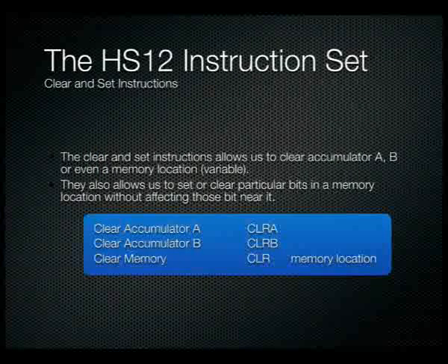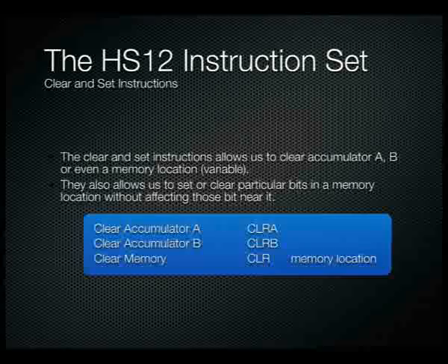We also have a series of commands that allow us to clear and set registers. We can clear an entire register, we can clear bits in a register, and we can set bits in a register. We've got two different types of resolution here. We can do register-wide clear, or we can do bitwise setting and clearing. The commands that allow us to clear an entire register are the clear commands.